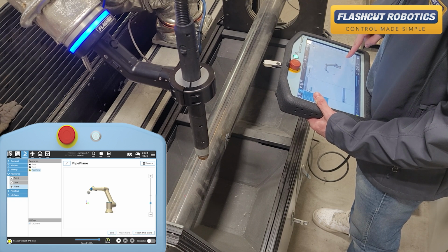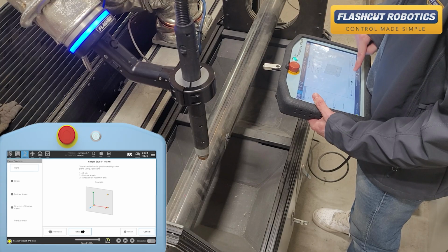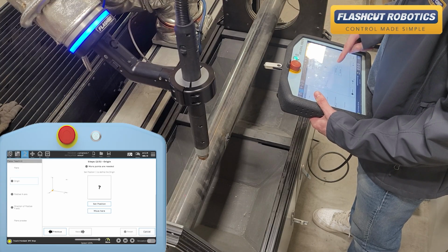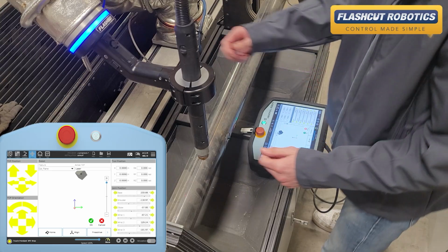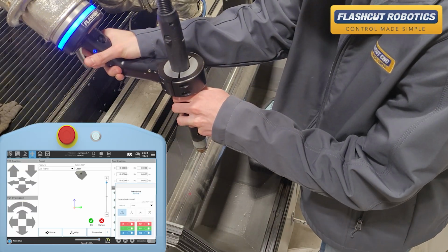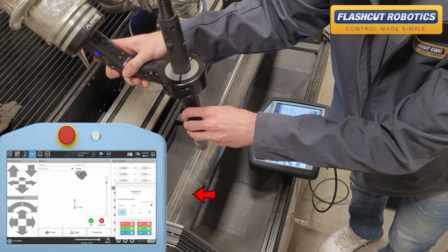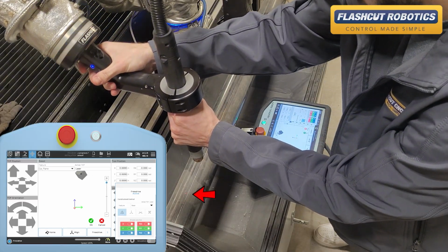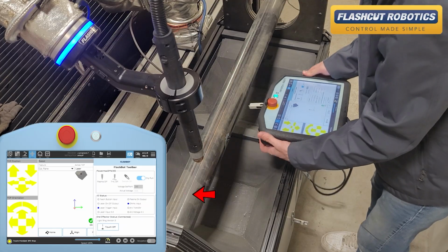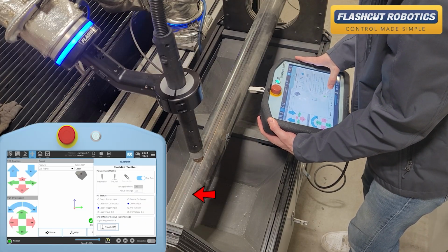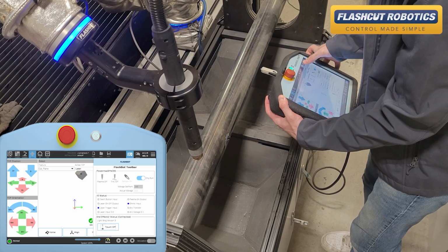Before teaching, make sure your active TCP is set to the laser. You can also confirm this in the Move screens during teaching, and ensure Pipe Plane is selected as the active feature while jogging. For the first point, position the laser at the highest point of the pipe, where your program 0 will be. When you are happy with your laser position, open up the toolbar and click Touch Off. Then check this in as your origin point.